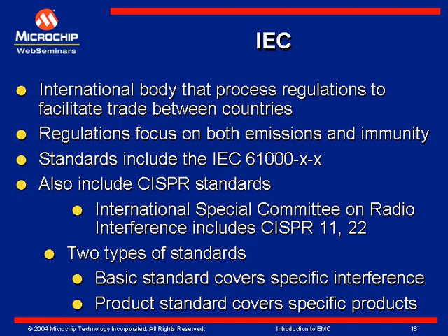The most popular standards in IEC are the 61000 series. There are lots of standards in this particular series that address various popular instances of EMC. It also includes CISPR standards, the International Special Committee on Radio Interference, which includes CISPR 11 and 22.